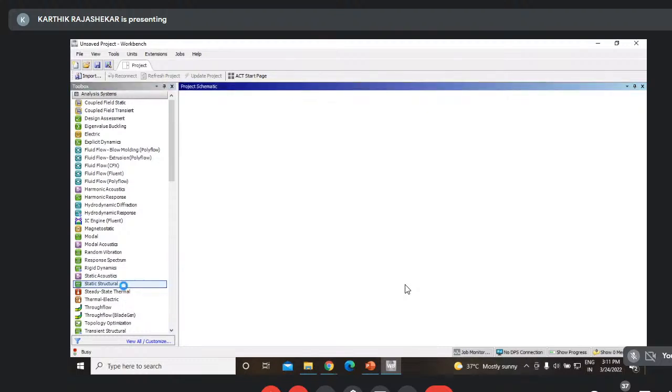I'll go for static structural analysis. Now again, the material which I want to analyze, I won't change it. If you want to change it, I've told you the steps which you need to follow. And now I'll try to import my model in order to do the topology optimization. You have seen in the earlier case where I modeled the geometry. After modeling the geometry, I extruded it, then performed certain computation, and generated the result. So that is one procedure.